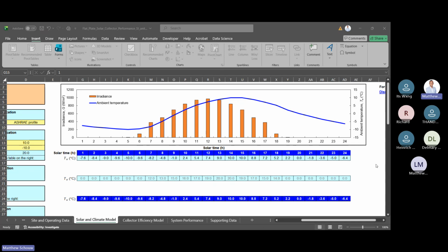What you can actually do is go to Excel, put in a trend line, and go to more options. A trend line develops an equation for the graph, but you can go to something called polynomial, and you can raise the order of the polynomial to a more accurate one. So let me just delete the straight one. Can you see this line here? I try to fit the graph. Excel is not the best software to fit lines, but it's definitely one of them. For a case like this, it might be good enough.